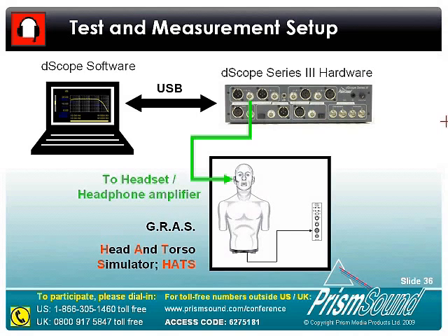Again, the reason for doing so in this case is because I'm interested in analysing the performance of just the electroacoustic components, and I want to isolate them from anything else that might be upstream, including potentially equalisation, as we saw in the previous example. I just want to look at the electroacoustic performance. So I'm taking the output from the microphone power supply and connecting that to the input of the D-scope hardware.